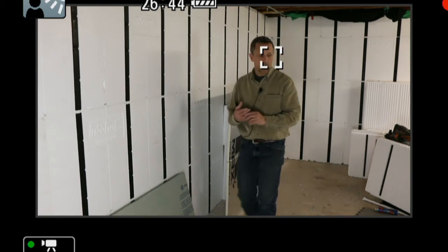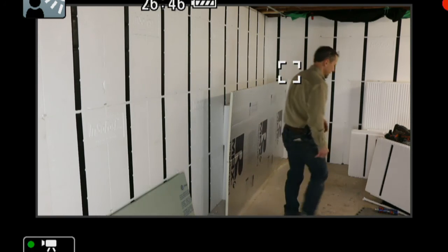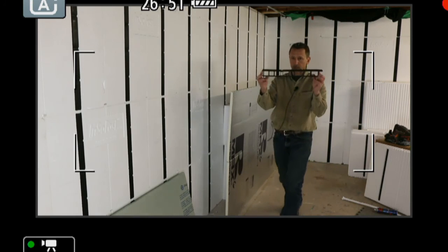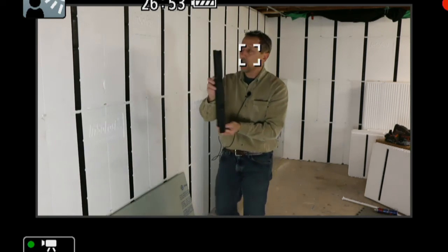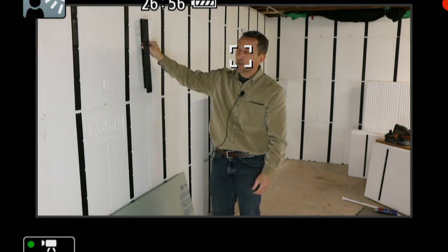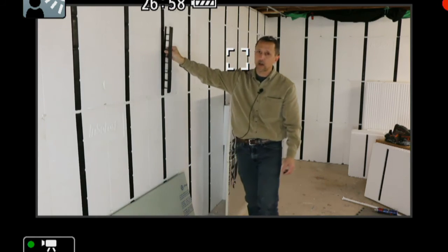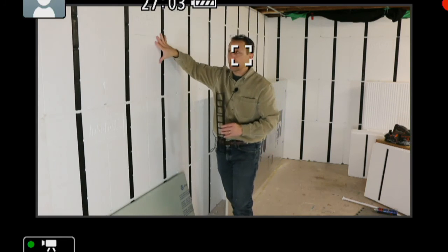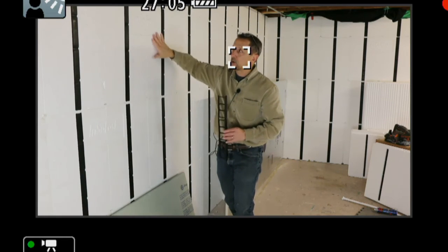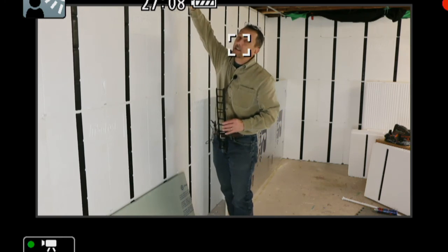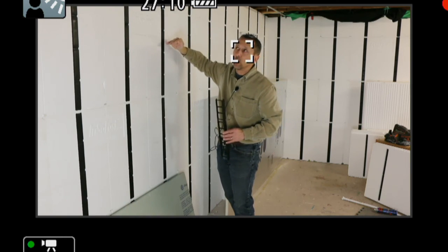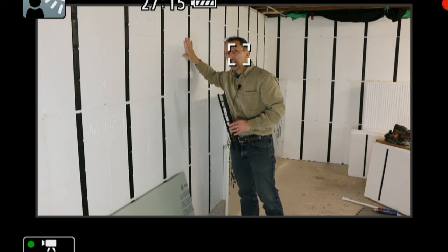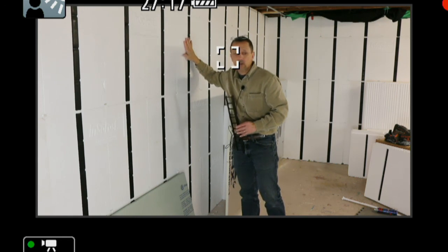Because what you're buying with InSoFast is the ease of application. And the ease of application really is this piece of wonderment. This is the stud that's embedded in each one of our panels, 16 inches on center, that is really holding the drywall and the cabinets. This is like a regular 2x4 stud. It just doesn't have to carry the weight of the upper floors. It's a veneer insulation, a tiled insulation that takes all its structural strength from the concrete wall.